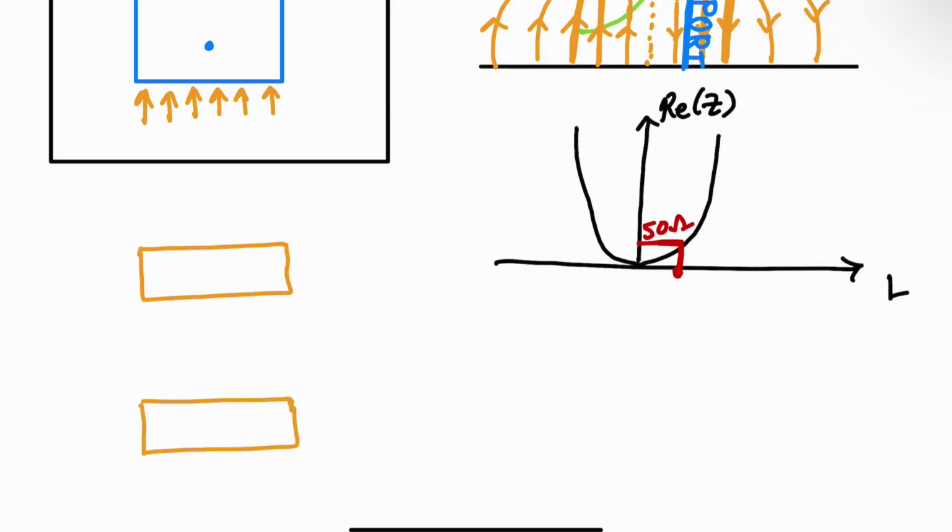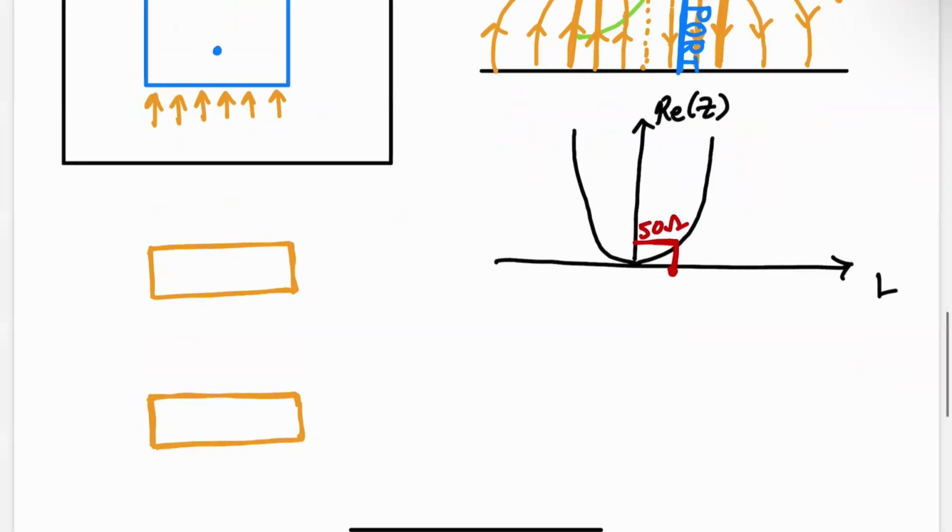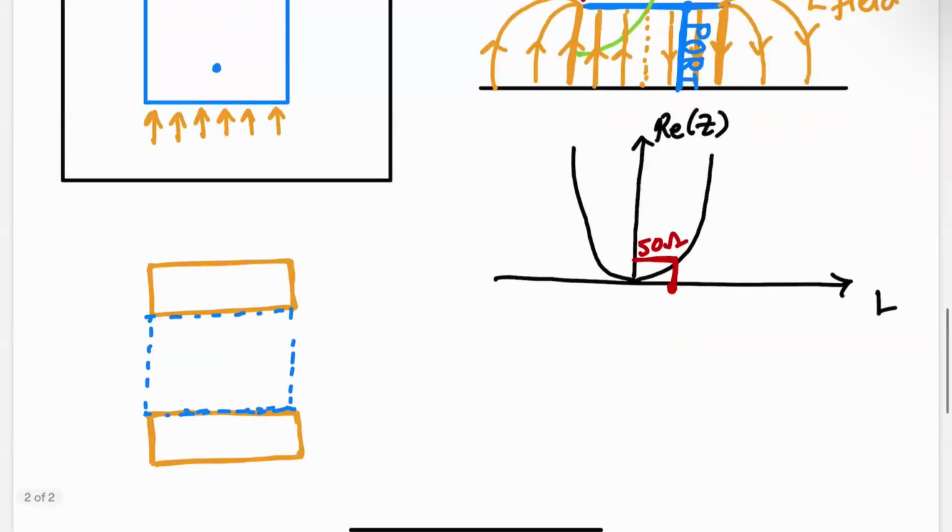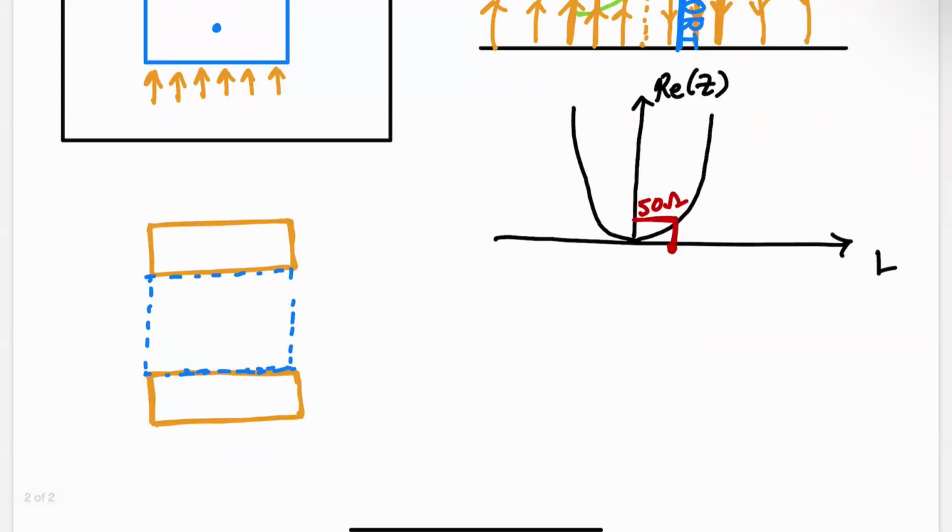And we looked at slot in the last class. So this is one slot, and this is the other slot. So you can say, okay, it's either radiating as two slots, and that's one way to look at it. And that's in some sense the most intuitive model, right? So this is your electric field. And these slots are separated by approximately lambda over 2.